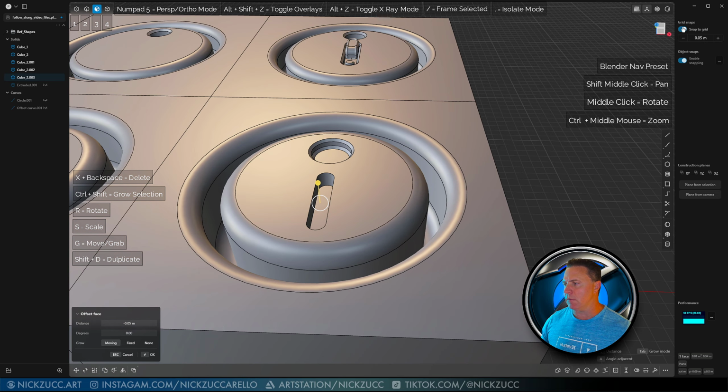this degrees that you see here by just controlling this here, I did find that I was getting better results using this as an option. And the reason I'm doing that, I want to do this tapering effect that you see here, and I think that's kind of a cool look. So I'm going to go ahead and hit OK for that. And so that's a little bit of a difference, at least what I've found, between doing the offset and then actually using the extrude function on there.